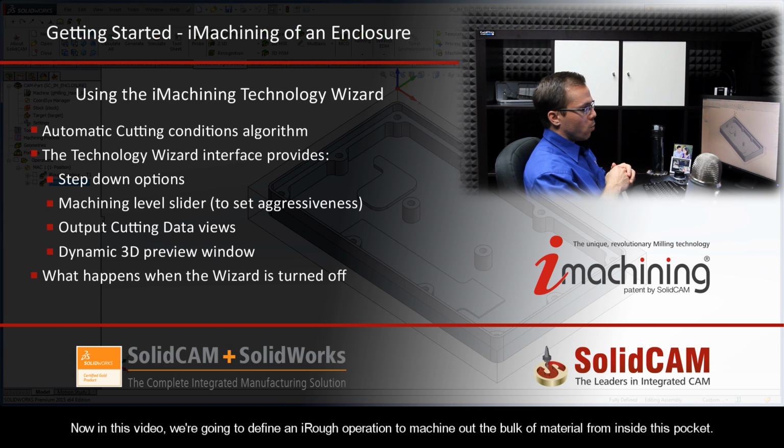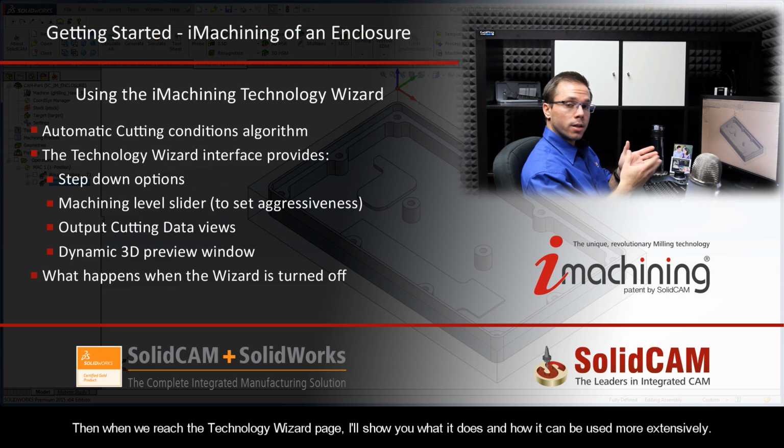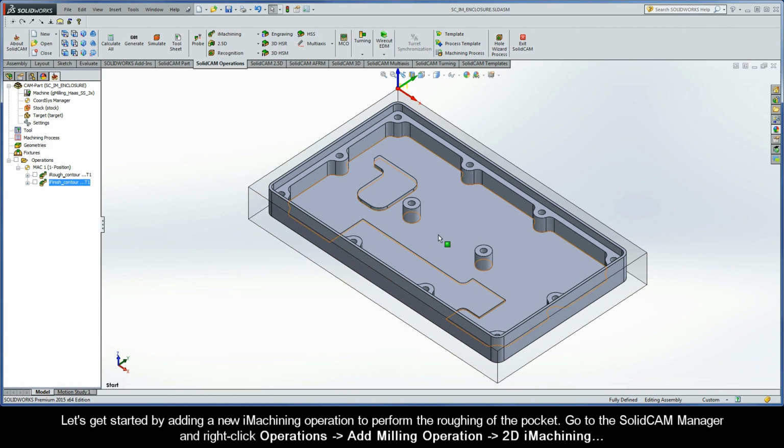Now, in this video, we're going to define an iRough operation to machine out the bulk of material from inside this pocket. We'll do everything that we would normally do, which includes completing the geometry, tool, and levels definitions. Then, when we reach the Technology Wizard page, I'll show you what it does and how it can be used more extensively. So let's get started by adding a new iMachining operation to perform the roughing of the pocket.